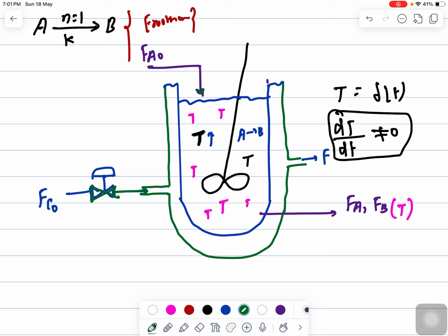what kind of things can be applied here? You will use a controller system here, and a temperature sensor, let's say TC1, and it will measure the temperature of the reactor, and another temperature control system will measure the temperature of the coolant, right? Now this will be connected like that, and after that it will give a signal to this control valve, right?